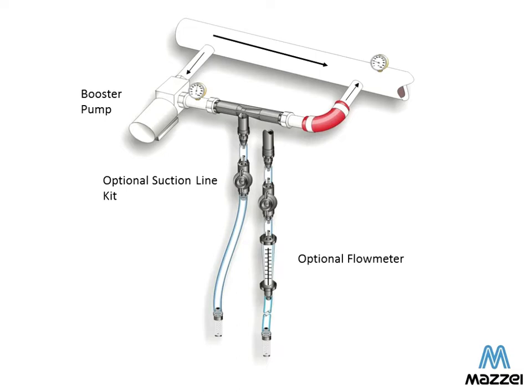One thing I might add is that utilizing Venturi type injectors for putting additives into the irrigation system allows you to have a continuous feed. At the same time, you'll have a thoroughly mixed water fertilizer mixture going into the main line, and that's usually desirable for good distribution out in the field.